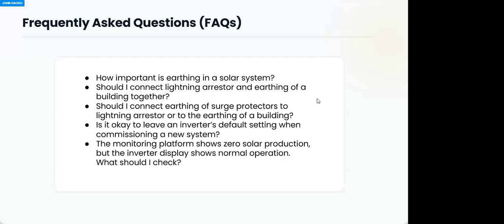Here are the most important settings to be done. Charging current of the batteries. Bulk charging voltage. If it's not communicating, if it's not lithium ion, you will set this. Charging current, bulk charging voltage, float charging voltage, low battery cutoff points. If you don't set this, you over-discharge the battery, and then it will kill the battery. So those are very, very important, and those are the first things you need to look at.